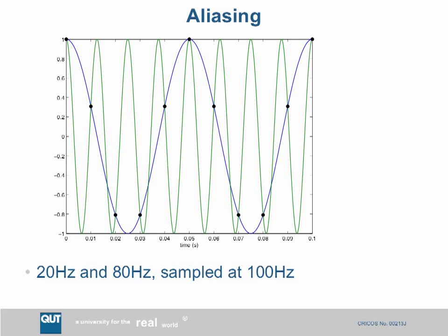If your sensor is something like a gyroscope or an accelerometer, mounted on a machine like an aircraft that's got a lot of engine noise that might be higher frequency than the rate at which you're sampling, then what you do is you mount that sensor on some sort of elastic material. So you create a mechanical filter so that those high frequency components don't get into the sensor in the first place. So there's a lot of ways you can get rid of this high frequency information, and we'll touch on these again in a later lecture. But that's called an anti-aliasing filter, and it's a really critically important part of any system where you digitize a continuous signal into an A to D converter.